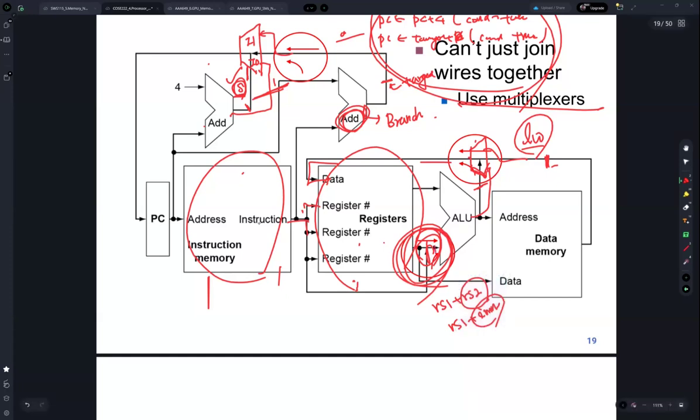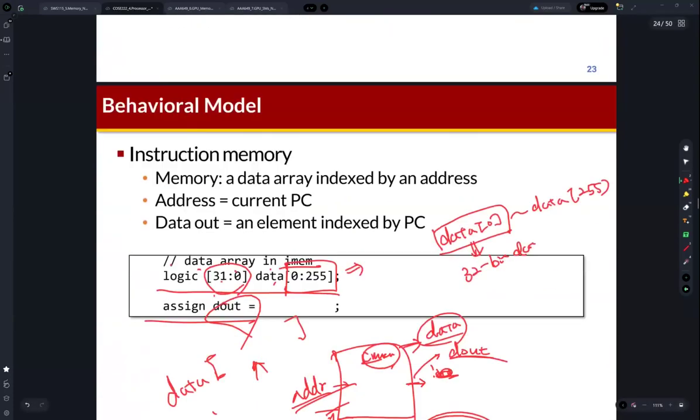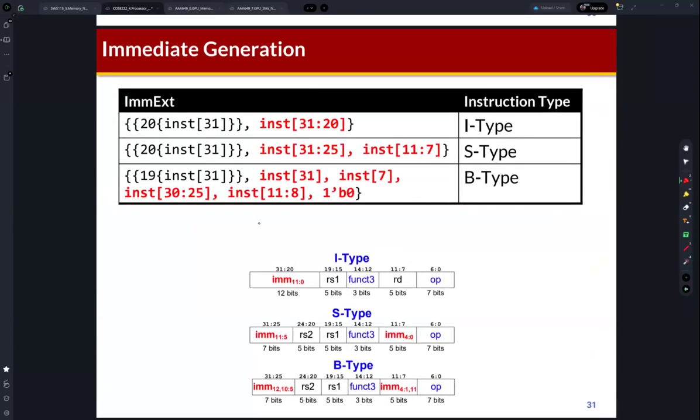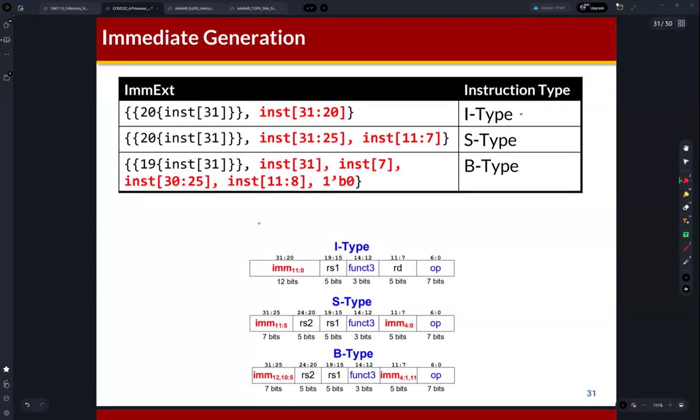Then what is the input width of this second port of the ALU? It is 32-bit, because the RS2 data is 32-bit. So from the immediate field, we need to generate 32-bit immediate data. But the I type just includes 12-bit immediate data. So what is required? Bit extension is required.